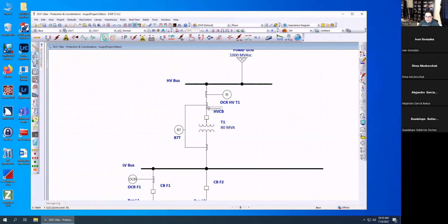You're going to have to figure out your CT ratio based on 150% of your load current. You've already done building CTs, so there shouldn't be anything new about that. Oh, I'm sorry, that's 100%. I meant you should choose the CT ratio to closely match the load current, without going over 5 amp secondary. So let's assume you did all that.